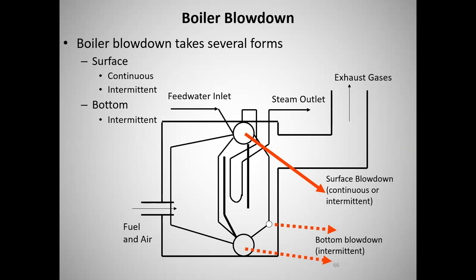And then they will take conductivity readings on every shift to look and see where they are. Well, they may have a set point of 2,500, and so what happens is when they blow that thing down like that, they'll drive it down to 2,000 or 1,800, and then over the course of the remaining shift, it'll come back up, and it may get up to 2,500, may get a little bit above, something like that, and they continually drive it down, and it continually seesaws up and down. So the result is that you blow down more water than you need to because you want to keep it below that set point.